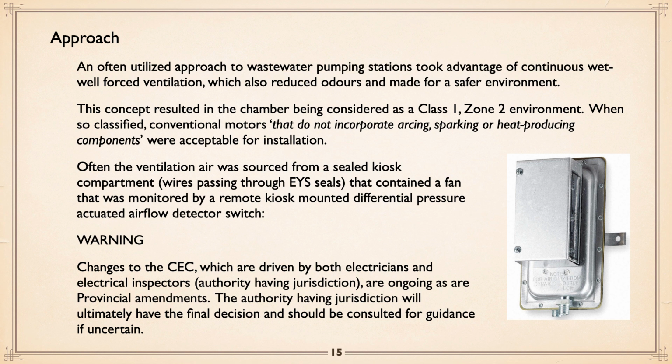And you can get these devices that operate on very low pressure, and you can mount it in a kiosk, and literally the sensing differential on the one side is the kiosk air, on the other side you sense it to where the kiosk chamber is actually being vented, and that little difference, which is very, very slight, is enough to trip the switch. And if you've got a normally closed contact, fine. And when it fails, the contact will close. Boom, you've got your alarm.